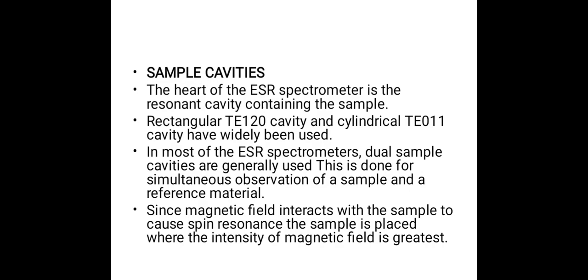Sample cavities. The heart of the ESR spectrometer is the resonant cavity containing the sample. Rectangular cavity and cylindrical cavity have widely been used. In most ESR spectrometers, dual sample cavities are generally used for simultaneous observation of a sample and a reference material. Since the magnetic field interacts with the sample to cause spin resonance, the sample is placed where the intensity of the magnetic field is greatest.